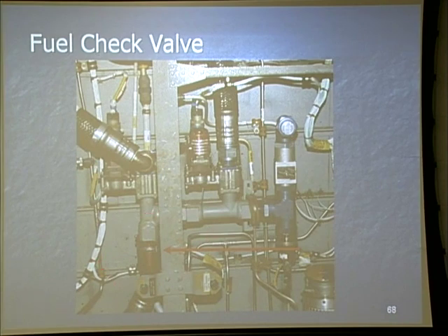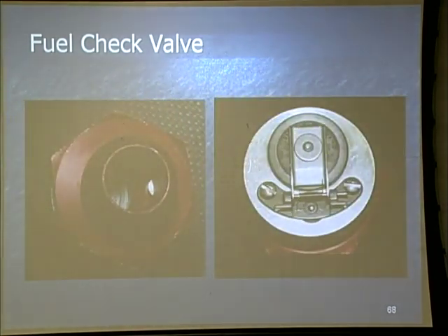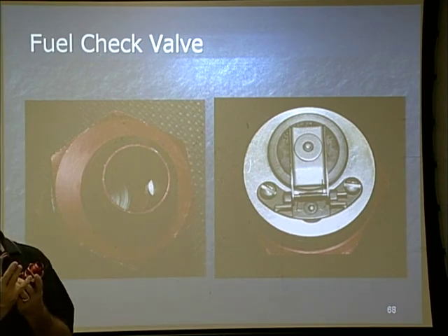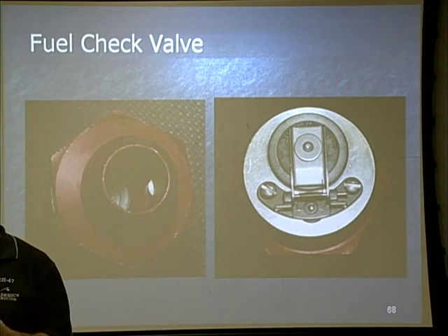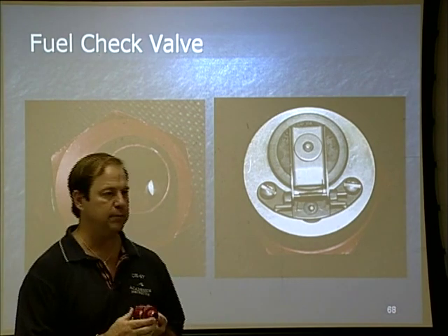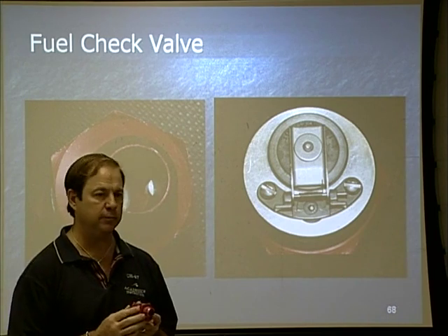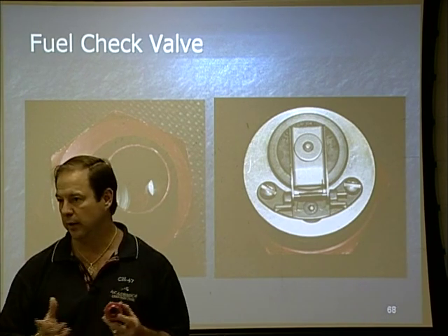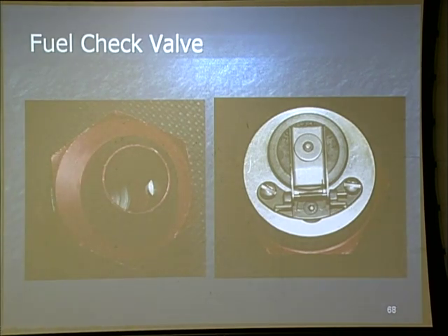And when we show you that one-way check valve, it does have a bypass capability in case of a thermal. In other words, if that line heats up, you have a bypass capability to allow that pressure to bleed off. Otherwise, you'd risk overpressurizing the system.